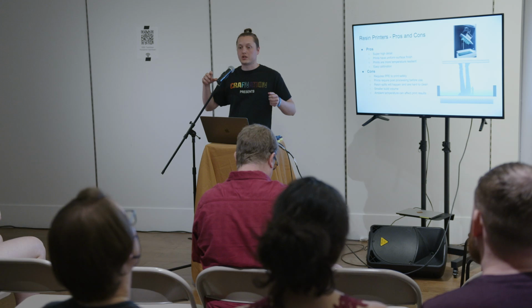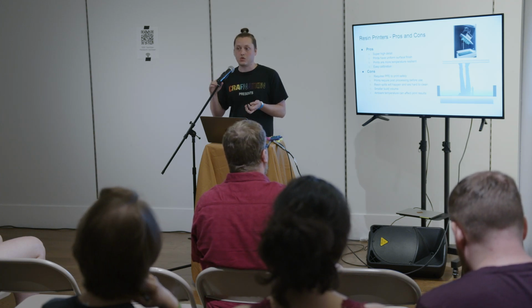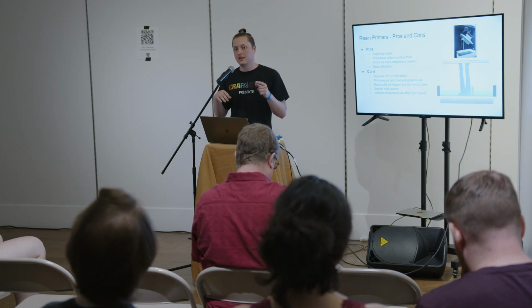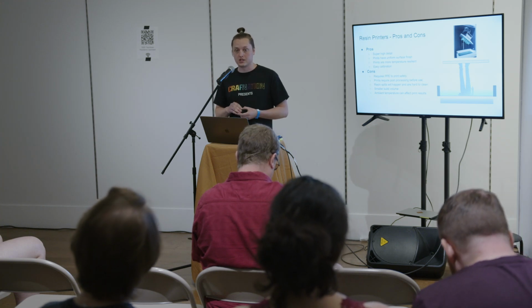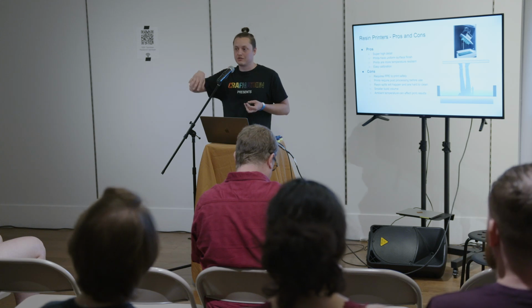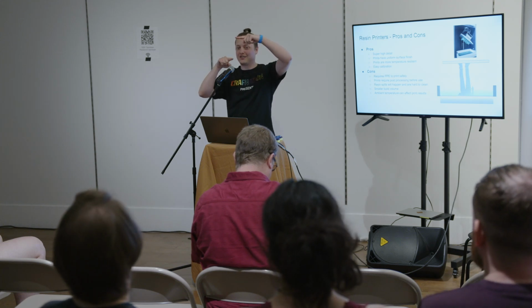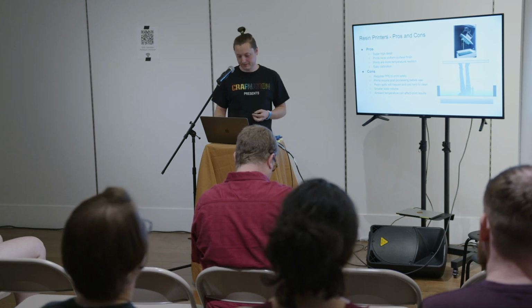And then there's temperature. If you're printing in a garage or an outdoor space or somewhere that has big temperature fluctuations, that can actually change what your layer cure time should be. So you can have some interference with the consistency of prints, especially if you start a print during the day and it runs overnight. You might see artifacts of that in the print as things get affected by that temperature change.